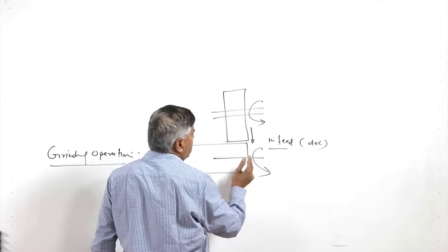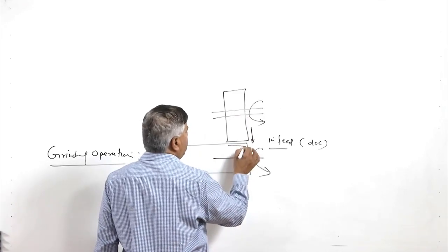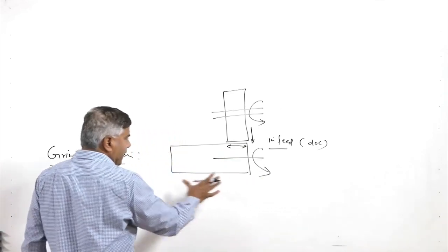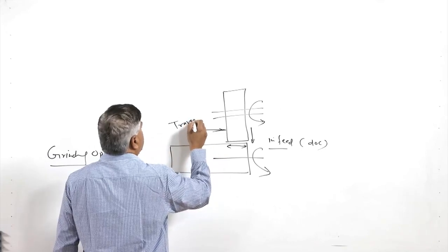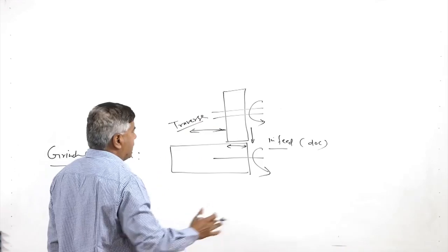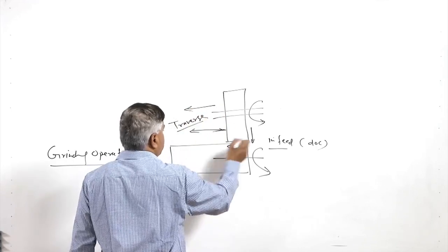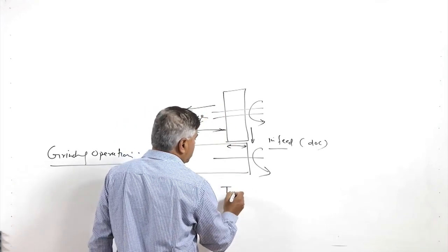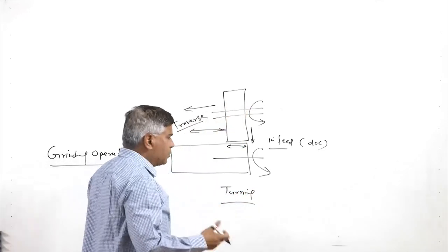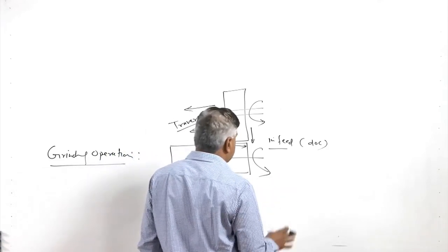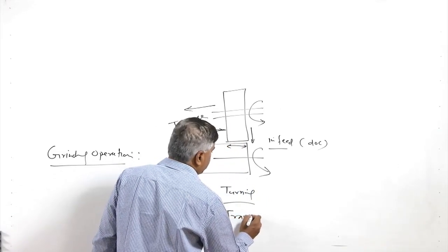but during this situation of the grinding, when the grinding wheel interacts with the workpiece, only this area will be processed. So, in order to cover the entire length of the workpiece, it is fed traverse wise also. So, traverse movement of the grinding wheel is given parallel to the axis of rotation of the workpiece. This situation is similar to that of the turning, where tool remains fixed, but here grinding wheel is a tool which is rotating. Rest of the movements are same as that of the turning. This kind of the grinding is termed as traverse grinding.